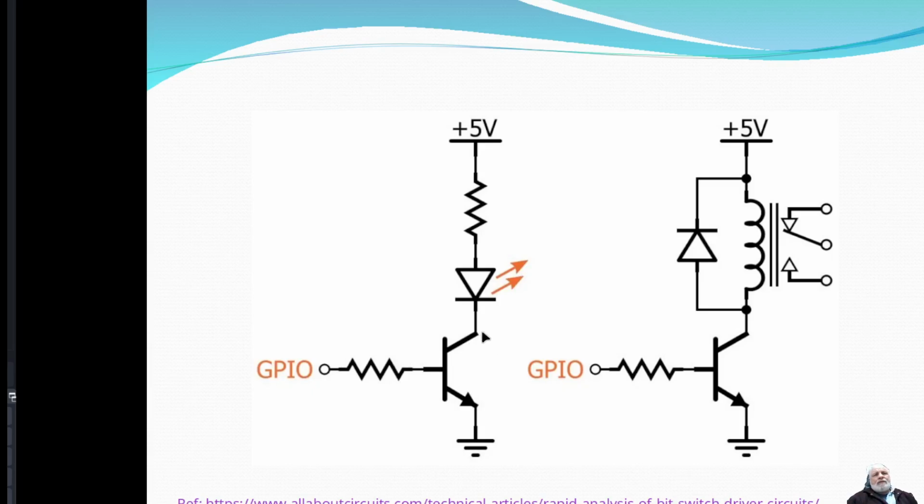And so then we've got 5 volts here. Depending on the color of your LED, you're looking at a voltage on the LED somewhere between about 1.7 volts for a red or green LED, 1.7, 1.8 volts. If it's a blue, it gets up a little higher, to about 2.1 volts or something like that.